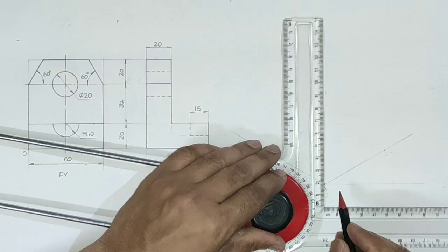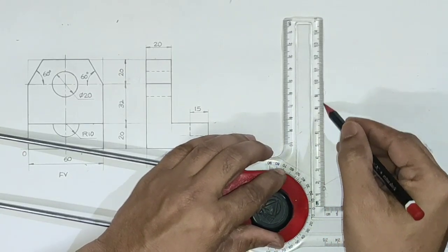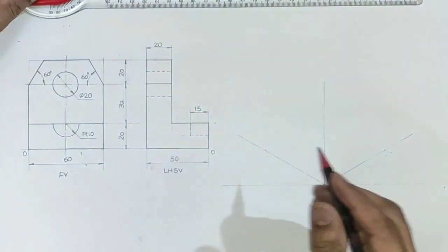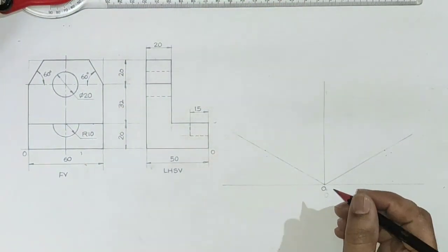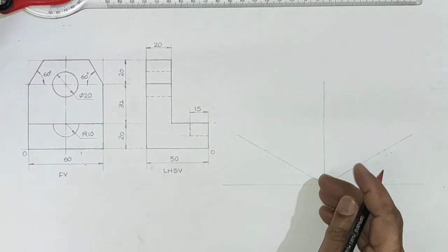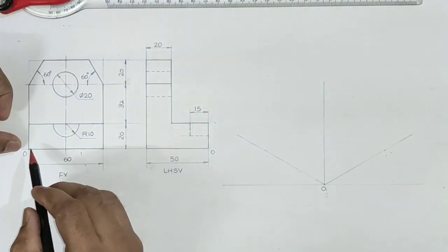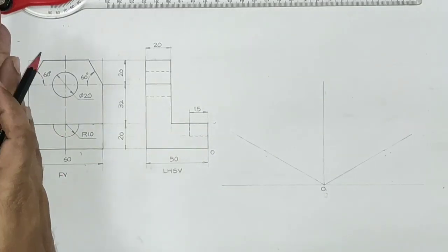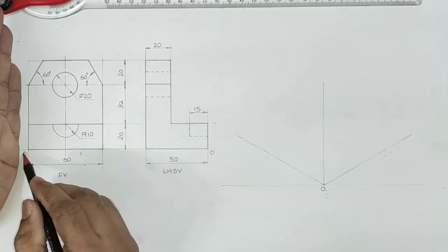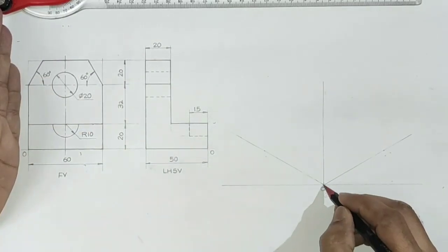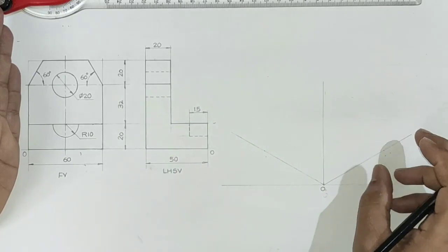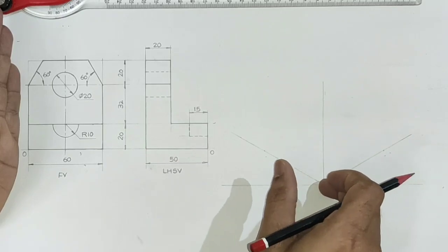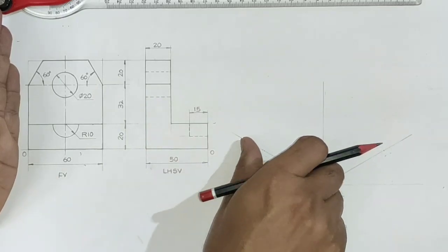then draw a vertical line through origin. Now let us take length, width and height along these three isometric axes. As we see in the front view, the entire object has occupied the space available to the right of origin. That's why we are supposed to take length to the right of origin. If the right side is the length, then definitely the left side of origin should be width.